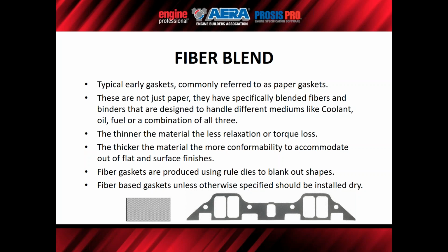Now, I know people like to put RTV on these things, and some RTV is okay. I don't recommend it, but you get people that think, hey, a little's good, a lot is better, and they smear it all over the place. That becomes a problem because then this gasket, when it's compressed, acts like a watermelon seed between your fingers. So you get that rubber coating on both sides, and when you squeeze it together, the gasket moves around. Well, it's only fiber, so fiber doesn't do well under extreme motion. It starts to destroy itself. So install dry unless somebody tells you otherwise.